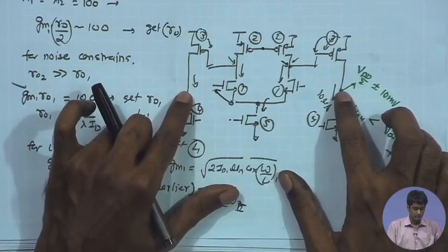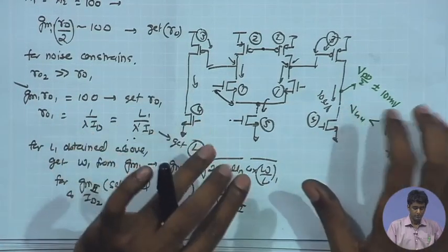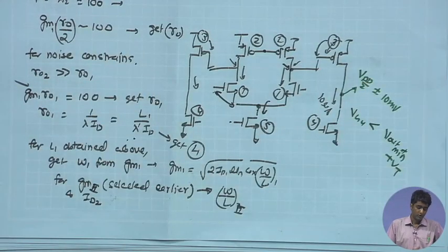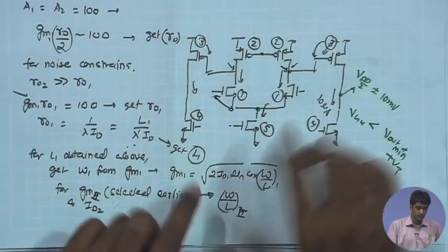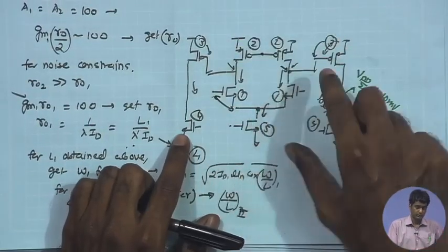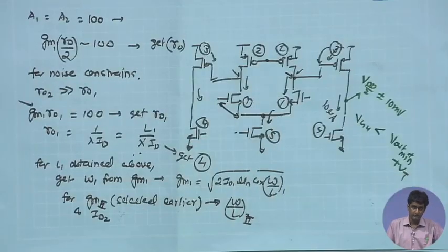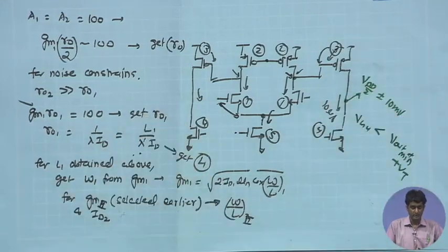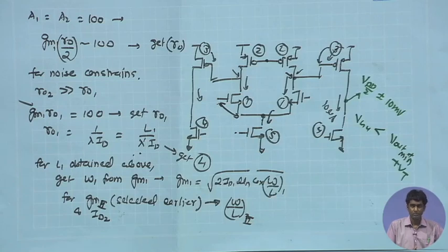And if we look at the input, if you look at the common mode feedback for the joint loop, like if you are having a single loop, and if you look at the common mode of the individual loops where you are requiring larger gain for the common mode feedback amplifier, there of course you are using current mirror load for that, and we are assuming GMRO gain from the common mode feedback amplifier.